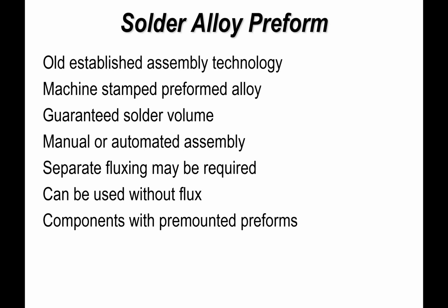Potentially, preforms come pre-fluxed, flux loaded, or they can be used without flux, and you're using those preforms in an environment which provides a fluxing atmosphere to clean the surfaces we're going to bond, and also provides the medium by which the solder flows across the surface.